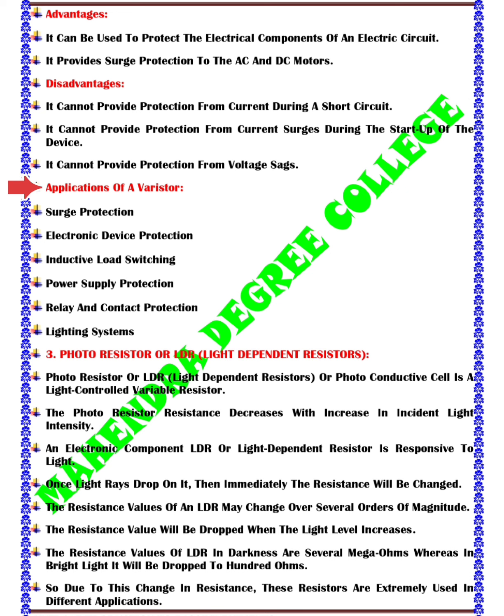Next, we discuss the applications of varistor. First one, surge protection. It means varistors are commonly used to protect circuits from voltage spikes and transients. When the voltage exceeds a certain threshold, the varistor conducts and diverts excess energy away from sensitive components, preventing damage.